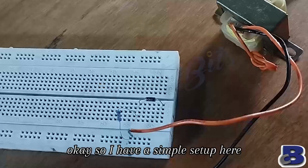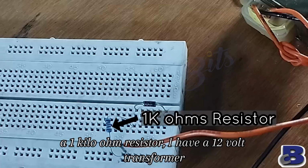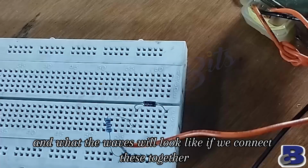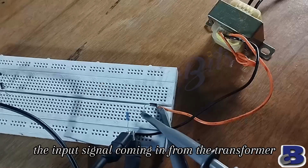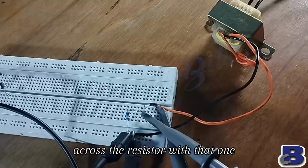Okay, so I have a simple setup here. I have the rectifier diode and I have a resistor, a 1 kilo ohm resistor. I have a 12-volt transformer. I want us to see exactly what we have just talked about, and what the waves will look like if we connect these together. So I have one probe to read the input wave, the input signal coming in from the transformer. I have the other one to read the output of the diode. We're going to be seeing the voltage across the resistor with that one.